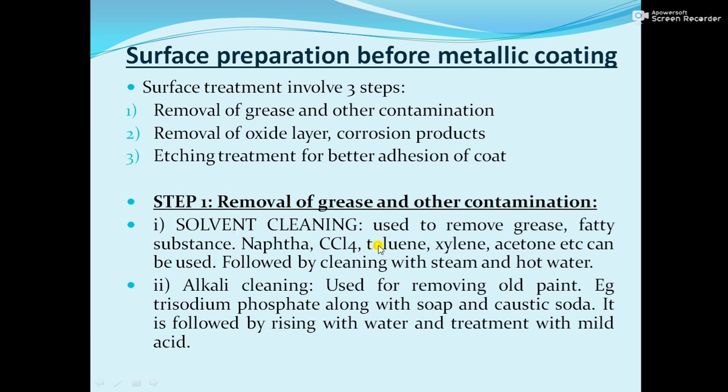It is used to remove oil, grease, and any fatty substance which is present. How is it done? Organic solvents like naphtha, CCl4, toluene, xylene, acetone, etc. can be used for cleaning. After cleaning, steam and hot water containing a wetting agent are used to clean the surface.